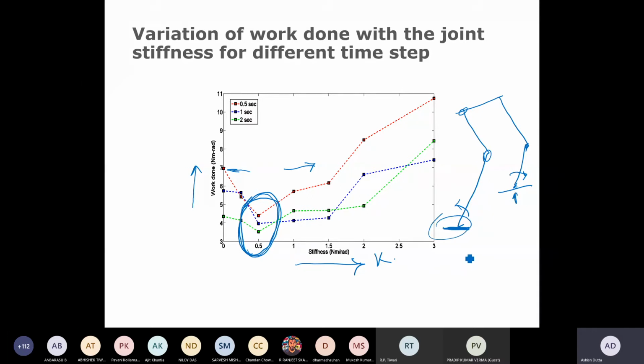But the next step, what will happen? It will reverse. If I draw it here, this leg has gone to the ground. Now this fellow is in air. So this fellow needs to become stronger and have higher stiffness. So this is fine, but then this has to alternate because the leg on the ground needs more stiffness and the leg in air does not need stiffness. And that is a challenge in today's robots.